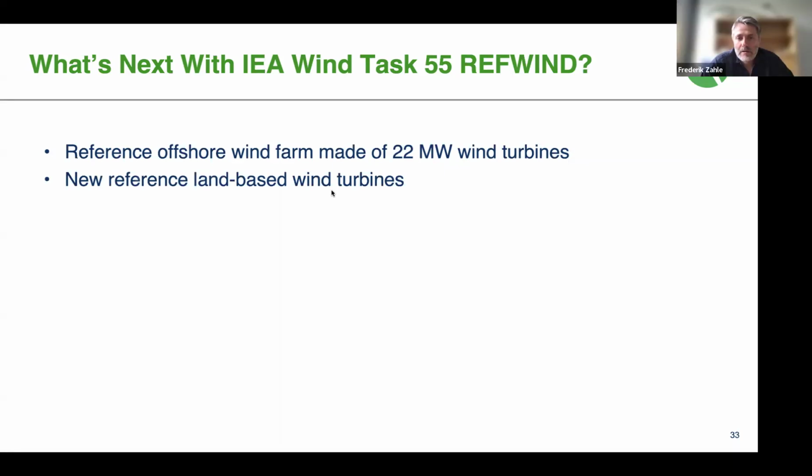For dynamic modeling, how was blade torsion modeled? This is done slightly differently between the different aeroelastic codes, but essentially it's a beam model that for all our cases could take into account the fully populated stiffness matrix, computed with cross-sectional finite element tools, in our case, BECAS. This is handled in Bladed, OpenFAST, HAWC2 and QBlade in fairly similar manners.